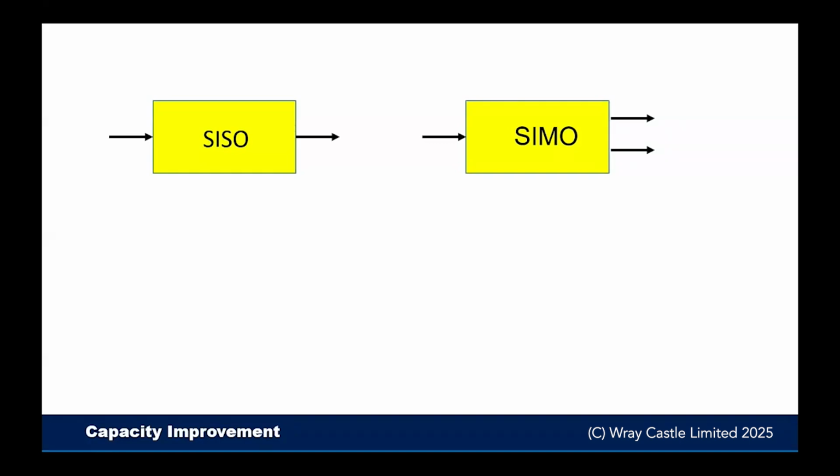One stage on from that is going to be MISO. MISO is a multiple input to the radio channel with a single output. It's sometimes called transmit diversity. It was a technique that was introduced into the 3GPP standards when the UMTS specifications came about, but I'm not aware of any mobile operators using transmit diversity. It would only be workable in a code division multiple access network. Otherwise, we'd have lots of multipath propagation issues.